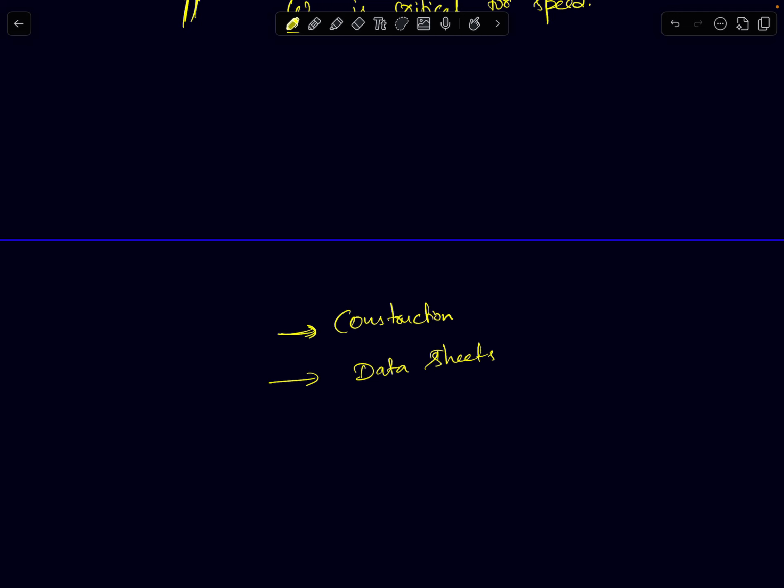And then we spoke in great detail about what the CMRR of an instrumentation amplifier depends upon, including the matching of the resistors, and we also showed that the gain error between the two op-amps in the first stage can cause CMRR degradation. So that usually gives us the specification for the DC gains of the op-amps. Then finally we spoke about the frequency response of an instrumentation amplifier, and we said the frequency response is usually dominated by the first stage UGB.